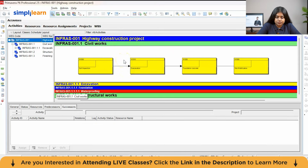So scheduling is the process of calculating the start and the finish dates for every activity in your project based on the durations and relationships you have defined. The algorithm Primavera P6 uses is the critical path method. It works in 2 mathematical passes through the network. The forward pass calculates the early start and early finish of every activity, beginning from the project start date and moving forward through the logic. And the backward pass calculates the late start and late finish of every activity, beginning from the project completion and working backwards through the logic.